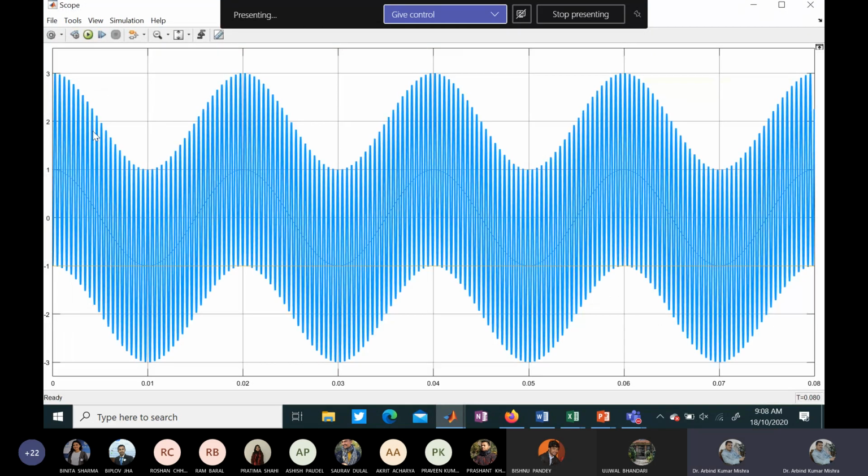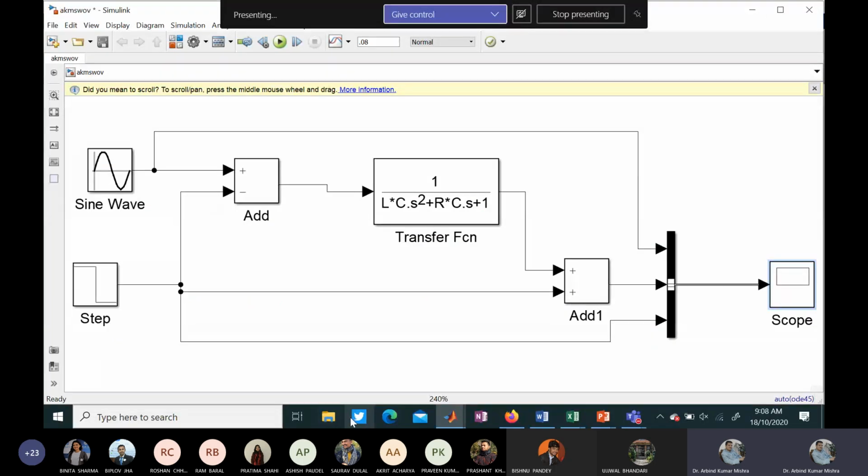No, you only see that the frequency of this oscillating transient wave has changed, but still the peak value is 3 pu. Since this is a lossless line, we have made R 0, that's why everywhere it is up to 3 pu. Just make it double.